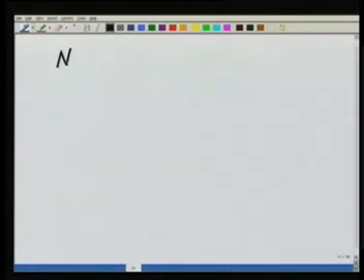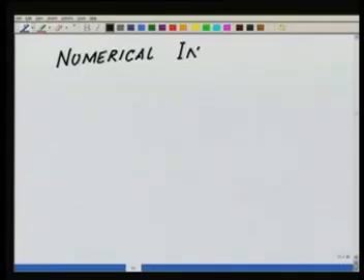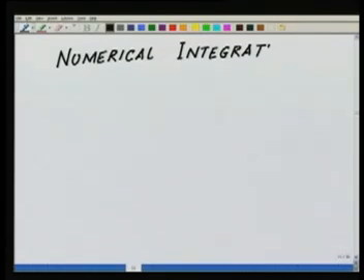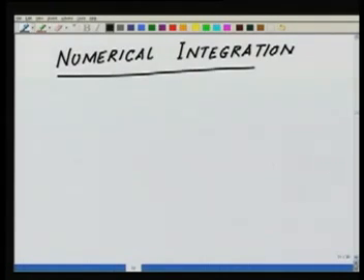Okay. Now the question is how do we go ahead and do the integration? Integration in a computational domain will involve numerical integration. So here we'll discuss the integration rules for triangles and quadrilateral elements. For a triangle, remember that we are doing the integral over the master triangle.